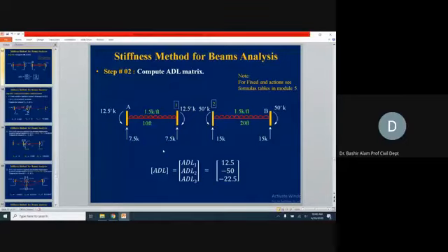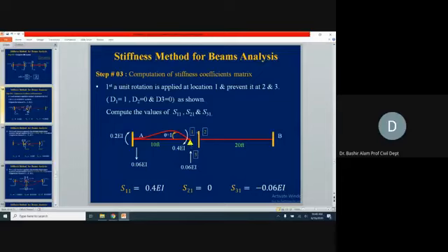Now, generation of the stiffness matrix. So how we generate it, turn by turn, we will be giving a unit displacement. Corresponding to D1, you see here, on the left side, we are providing a hinge support here. Rest, all the locations are fixed. At the hinge, the right side of this is fixed. That is 4EI divided by L, 4EI theta. So 4 divided by L, L is how much? 10. 4 divided by 10, this is how we get this action produced here, 0.4 EI.